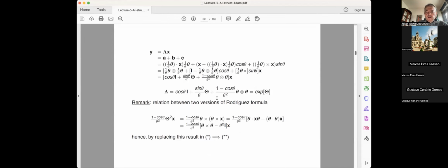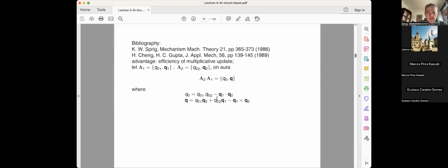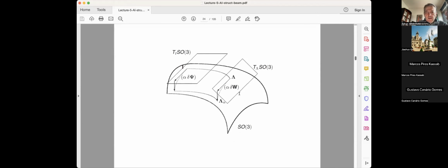the orthogonal tensor. Do I have an illustration here? Hopefully, for example, this will be the idea. SO3 is a sort of manifold. It's a curvilinear type of space, which is how you handle this skew-symmetric tensor. And then theta would be in the tangent space at the identity of this manifold. And then basically you can have lambda as the exponential of theta.